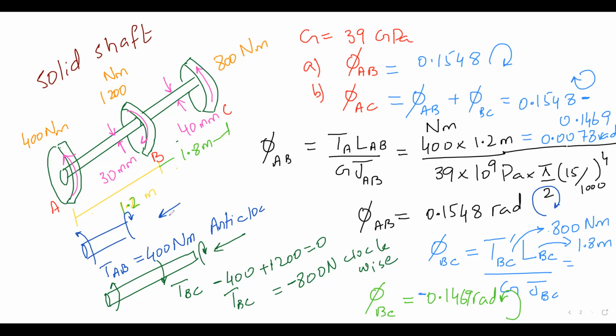For example, for me, the moment I cut from here, I know that the only thing appearing is 400 Newton meter. So whatever you do, you just have to write 400 here. The only thing you have to decide is the direction. If you look from here, it's pretty clear that if you're twisting it, this fellow will twist anti-clockwise. But since I have been looking from there all the time, it appears to me as clockwise. I know that the applied torque looks to me as clockwise, so I said twisting is happening in clockwise when you're looking from that direction.